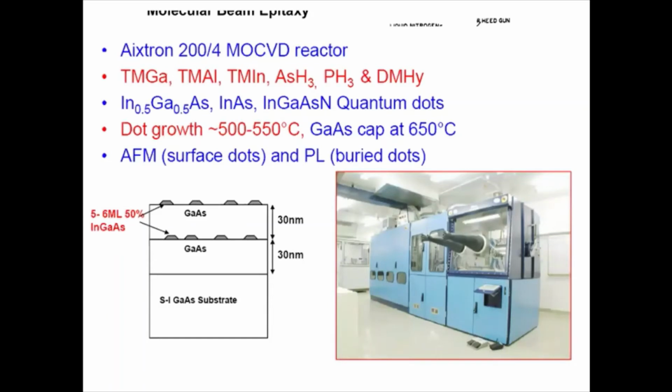So if indium gallium arsenide is deposited on gallium arsenide, for a specific composition they get lattice matched, because the lattice parameter for a specific composition of indium gallium arsenide gets matched with the lattice parameter of the substrate. In that case, the composition plays a dominant role. Substrates are mostly either gallium arsenide, indium arsenide or indium phosphide, depending upon the device you are trying to work on.